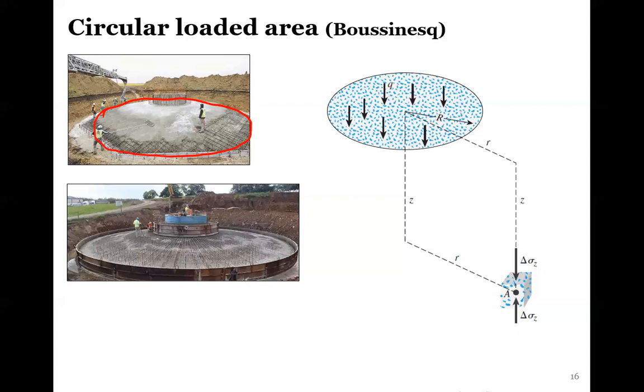If you're doing an octagonal area and assuming it's a circle, do you use an inscribed circle, or what's the name? Where it's concentric, or would you usually use an average? It depends on the project. You would underestimate, because if you underestimate the area, you increase the stress. So if you're unsure about the loading conditions, then it'd be safer to underestimate the area. If you're pretty confident, then you would use the average. So you wouldn't do the outer circle, you would connect the points on the interior or something. But yeah, good thinking. It's all going to be project specific and how confident the engineer is.